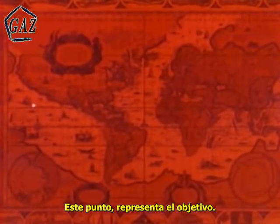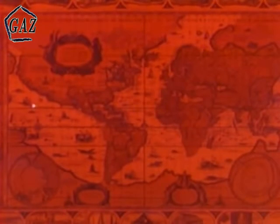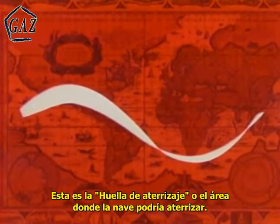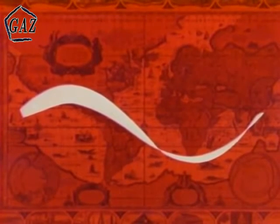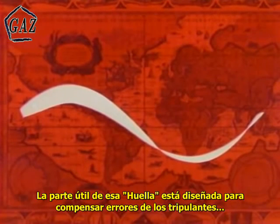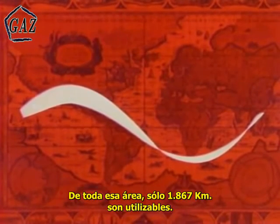This point represents the target, that is, the point at which the spacecraft should land. This is the landing footprint, or area in which the spacecraft might land, at the beginning of the first control period. The usable portion of this footprint is designed to compensate for accrued errors and to provide alternate landing sites in case of bad weather. Of this total footprint, only 1,000 nautical miles, or 1,150 statute miles, are usable.